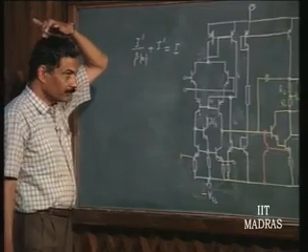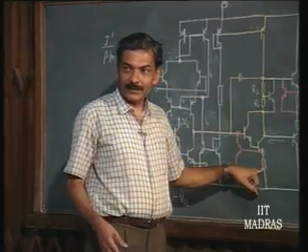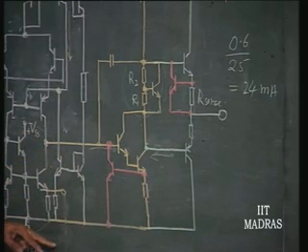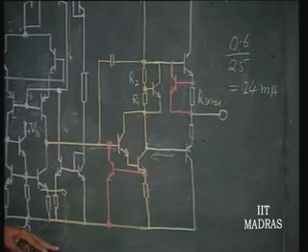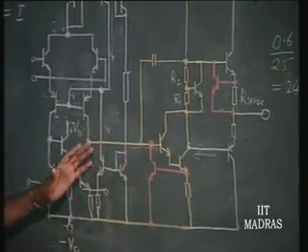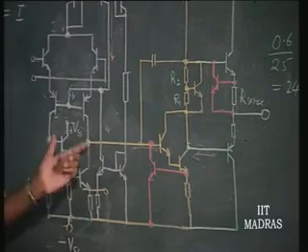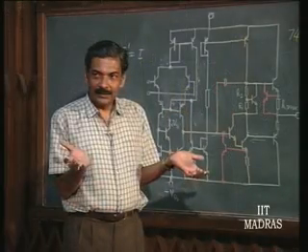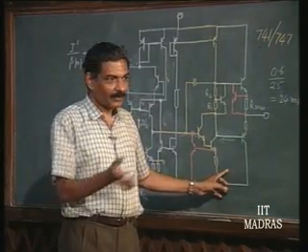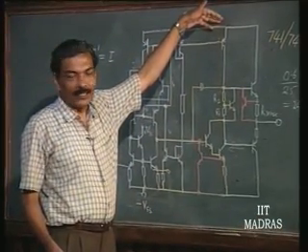Now, the gain of the intermediate stage is affected because of that. Correct. That is a point I forgot to point out. The gain of the stage is obviously getting affected here, but you just look, because the resistance is put here, okay, the impedance level has gone up here. Okay. So, actually gain is not going to get much affected, okay, because of this kind of scheme, right. The impedance level here has gone up further, so that means the gain of this stage has gone up by some amount. Okay. So, anyway, this is a low valued resistance here, okay, that is about 50 ohms, okay, and this resistance is of the order of hundreds of kilo ohms.